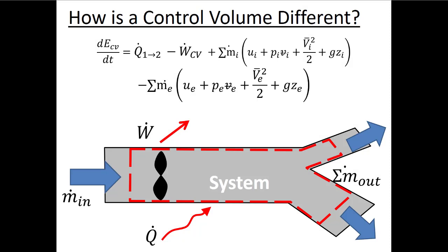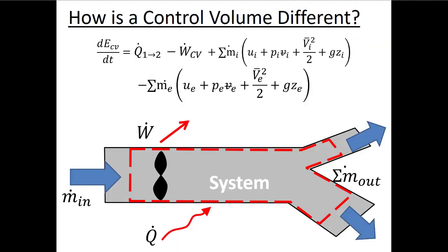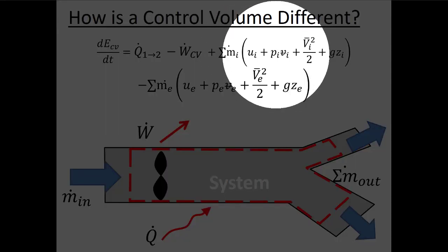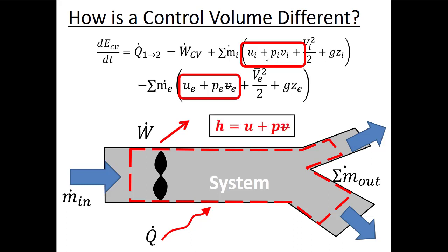But you've got to remember, as engineers, we try to be efficient. So here I've got this specific energy plus pressure plus specific volume term. Now, anytime I fix a state, I know all of these terms, because once you've fixed the state, once you have two independent intensive properties, you know all the intensive properties in the system. So I can make my life a little bit easier if I define a new variable here. We're going to take the specific internal energy plus the pressure times the specific volume, and define a new term. That term is going to be the specific enthalpy, symbolized by little h.